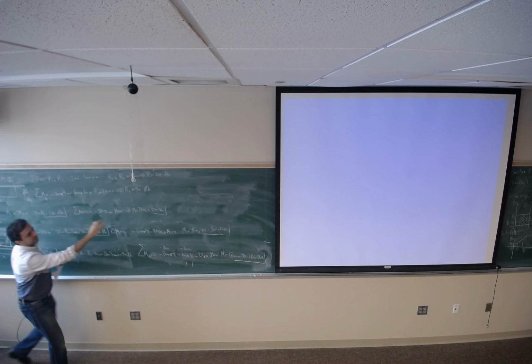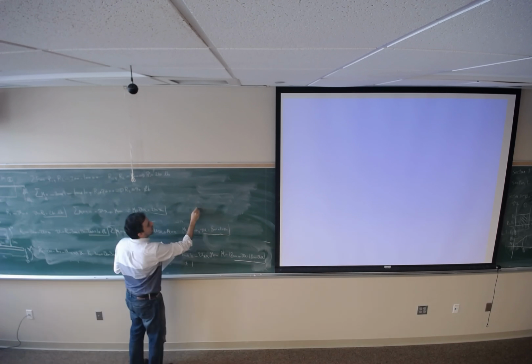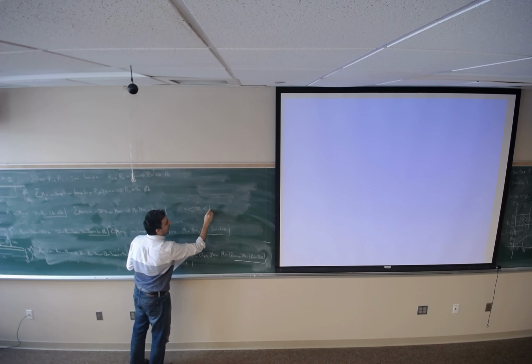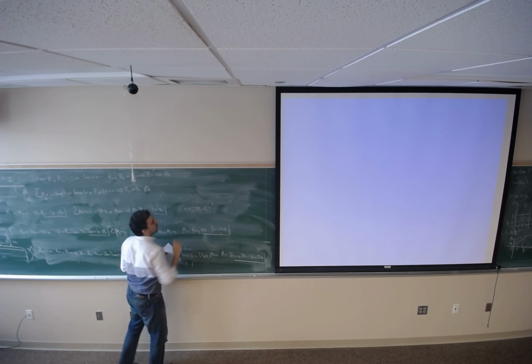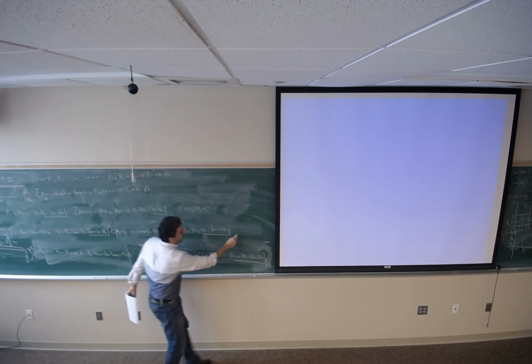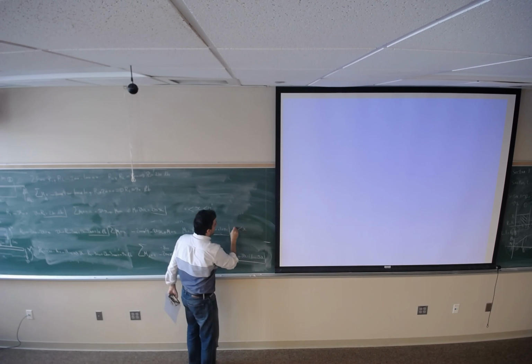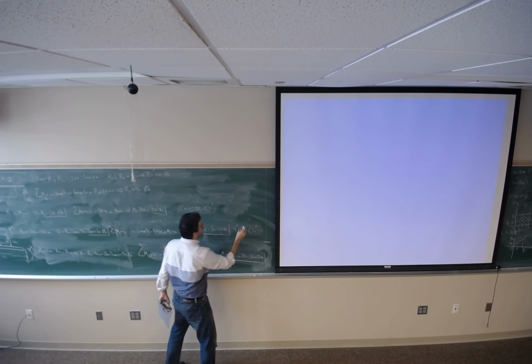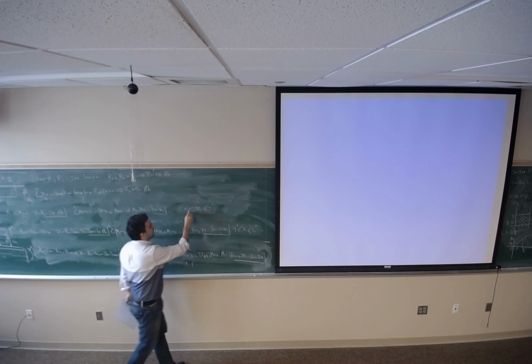This equation, this shear force, and this bending moment are valid for any X between 0 and 4 inch, because section 1 represents this part. Section 2 is valid for any X greater than or equal to 4 inch and less than or equal to 10 inch, from here to here.